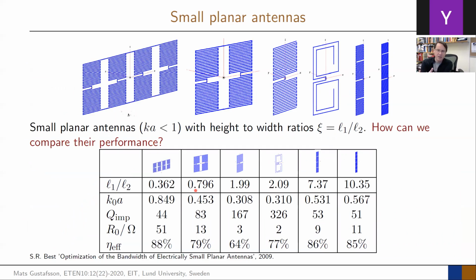So if we take that and look at some small antennas, really antennas that have shrunk their size compared to, for example, this dipole. The generic shape that we have seen before, and you have learned it, is that the first or simplest case is this type of meander line. So you take the length you have of this wire, but you try to fit it in a smaller size. Then we can see how they perform.